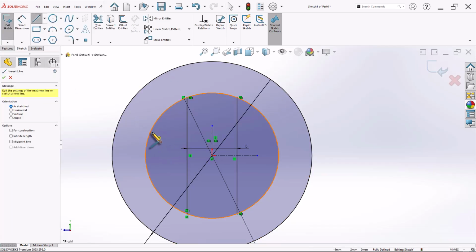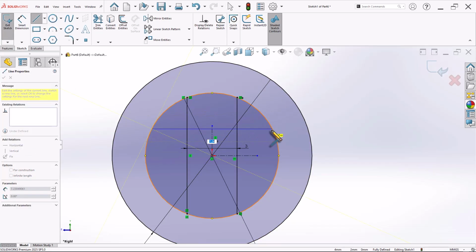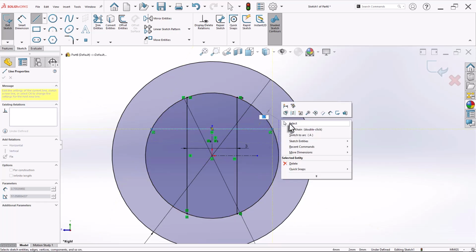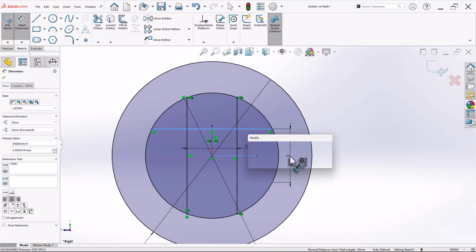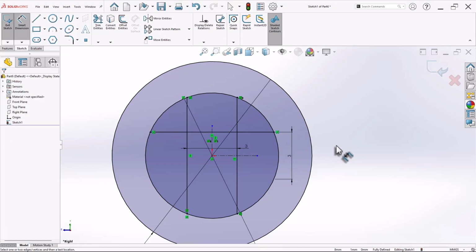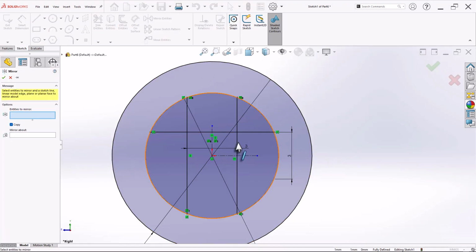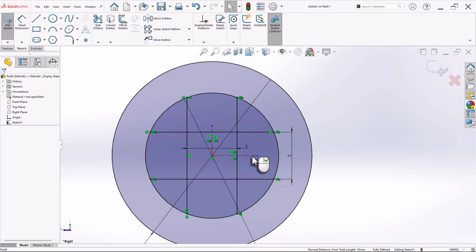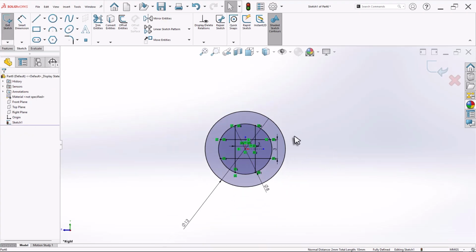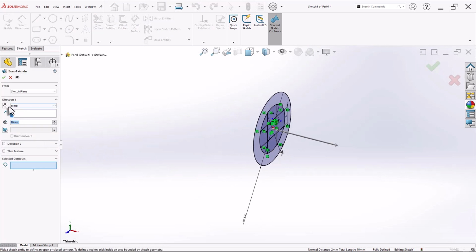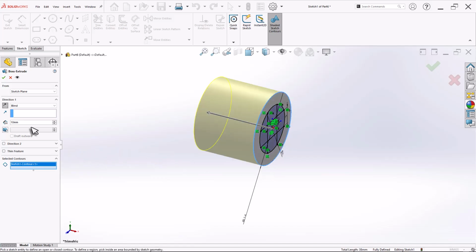Now let's do the other part of the geometry. So this should be 3 again. Now let's click on mirror, select this, right click, select this, right click. So this is the region we are going to use for extrusion. So press shortcut S and now let's extrude in the opposite direction this outer circle whose width is 3.